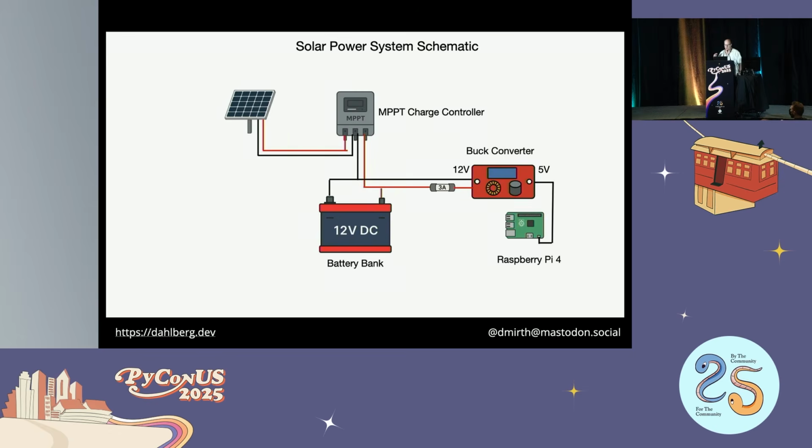The trick here is to appropriately size the solar panels and battery banks so that during a normal day of sunlight, the batteries will power the device and still have enough charge to power the device at night and on subsequent cloudy days. Next in line is the very important 3-amp fuse between the battery bank and the buck converter.